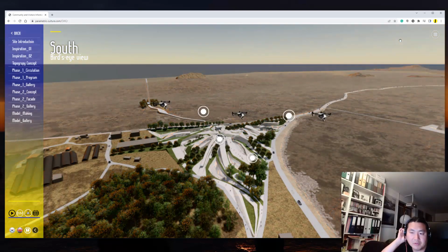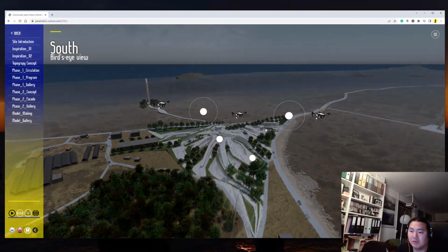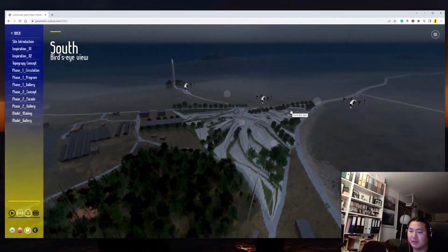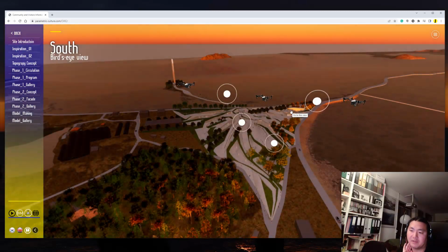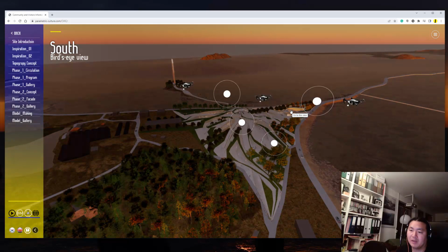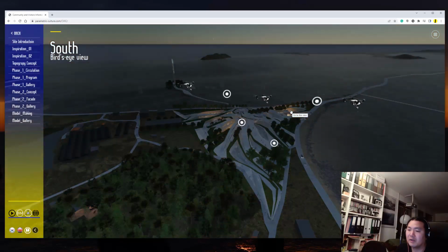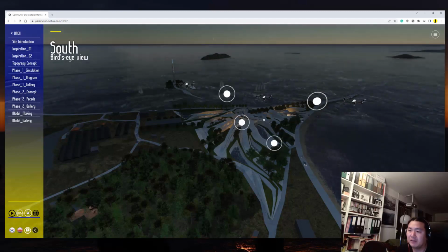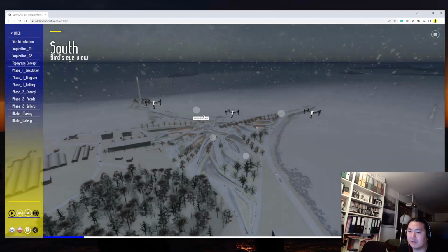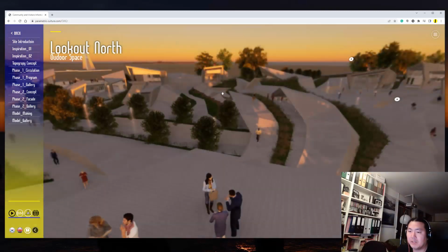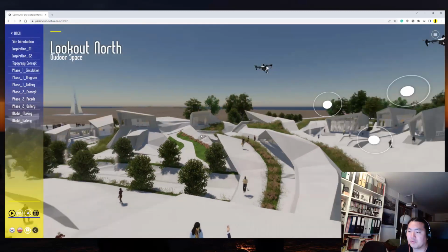Of course, back then there was no direct link between Rhino and Revit. So I had to use a Grasshopper definition and stream the data as a CSV file to generate topography in Revit. And also in Revit, there was a bit of manual geometrical operation I had to go through.